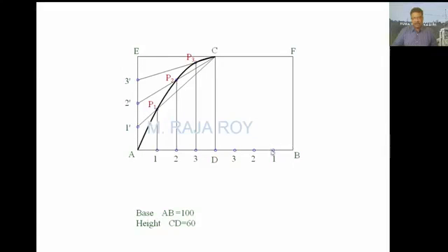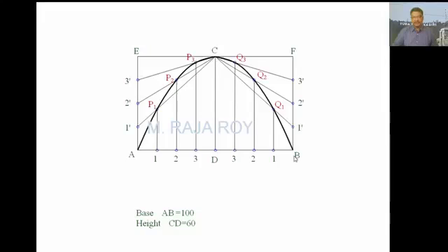Now this is your origin point. That's why you have to give the numbering like this, 1, 2, 3 towards your left and in the upward direction. Divide this into 4 parts and 1 dash, 2 dash, 3 dash. This is the origin point now. Now again draw the line joining C to 1 dash, 2 dash, 3 dash and from 1 draw a line parallel to CD like this. This is Q1, here it is Q2, here it is Q3. Now join them. Now complete parabola is ready.